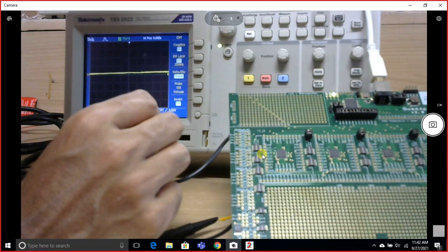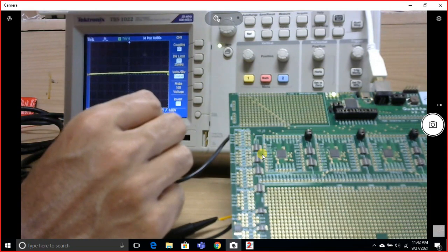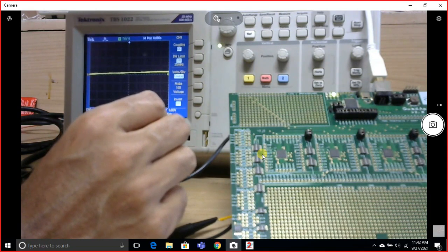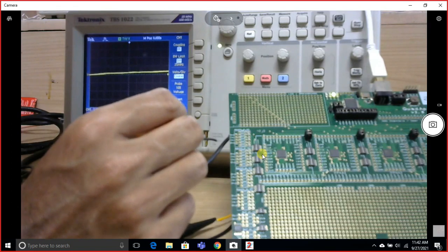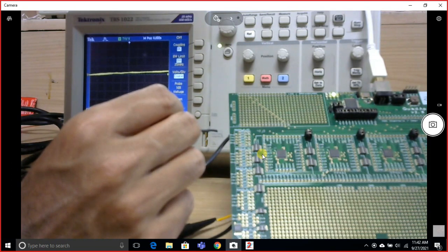Internally, the FPAA converts the single-ended supply into negative, a differential one. Otherwise we would have to give a negative supply as well. Since our design is based on a differential signal, we take negative as differential ground and positive internally.